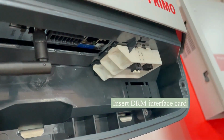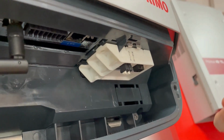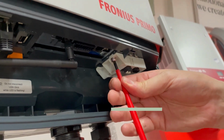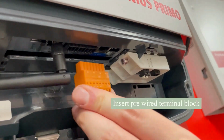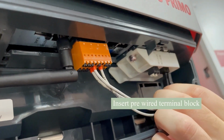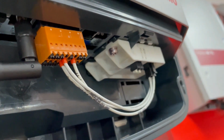So the next step is to put the DRM interface card into the bottom of the inverter here like that. And then you'll need to fit a screw that will go straight into here, like so, and that will hold it into place. Okay, so the next step is to put the orange terminal block in that came with the DRM interface card, and then plug the pre-wired connector into the bottom of the interface card.